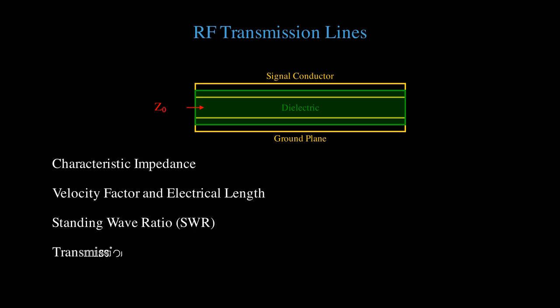load. Short sections of transmission line can function as circuit elements. A quarter wave line transforms impedance according to Z² divided by the load impedance. A shorted quarter wave line looks like a parallel resonant circuit, while an open quarter wave line looks like a series resonant circuit.